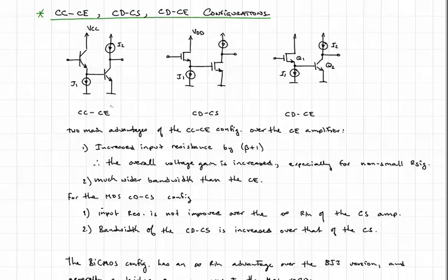We want to finish up this chapter by considering several useful amplifier stage combinations. So we begin with combining the common collector or common drain, otherwise known as the emitter follower or the source follower, with a common emitter or common source amplifier. And here we see some permutations. First, the two bipolar stages, then two MOSFET stages, and then lastly a bi-CMOS stage. We won't be analyzing these at this point. We're just going to look at some of the characteristics, what the advantages of doing this are.